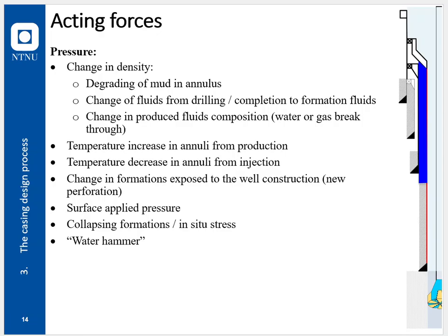Annuli here marked in blue, what is going on. We do again a worst case scenario. If the full mud weight as installed is the worst case, meaning like a collapse consideration, then we use the full mud weight. If it's a burst situation, we think about the mud as degraded. Normally,